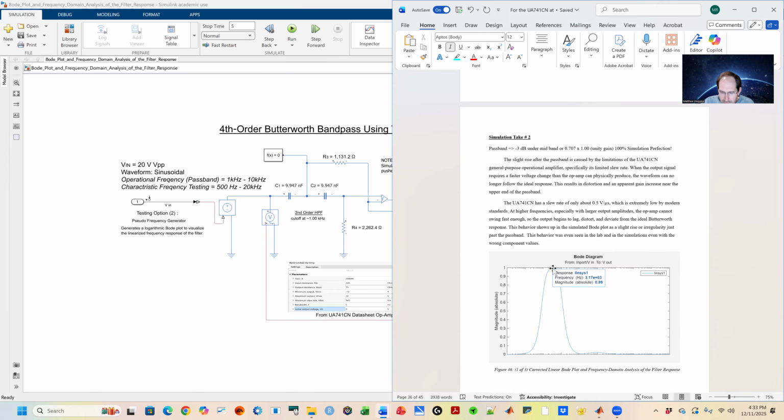So it's a really good thing to have if you don't want to have distortion and you're trying to take in specific frequencies. It's really good to use a fourth order or even an eighth order if you're really ambitious. This peak shows us the frequency where the circuit provides the most amplification as well. In the center of the band, the gain reaches its maximum. So that's the point right here. And it's the resonant region where the filter is designed to operate.